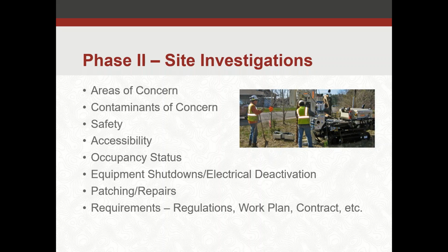Patching and repairs, to what extent do you need to patch and repair as you do your sampling? Certain facilities, if they're occupied and they're continuing to operate, you don't want to leave a mess behind. You don't want to leave chunks of building materials left out. You're going to want to do some patching and repair on that. Other facilities might not be as big of a concern. If you're going to demo a building within the next couple of months, maybe patching and repairing isn't really a critical item to do as you're going through that investigation process.